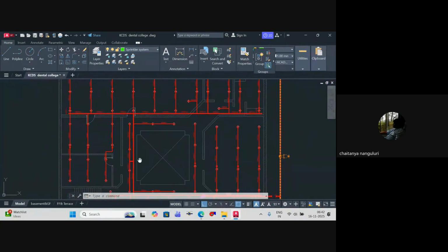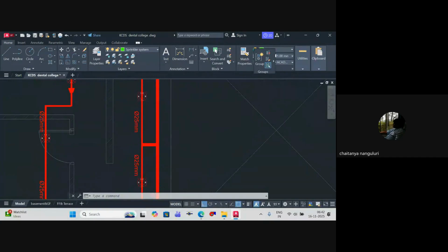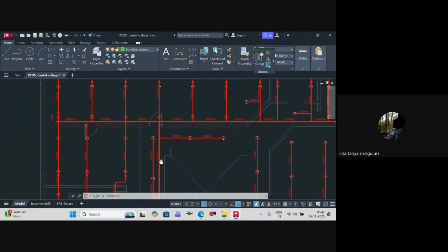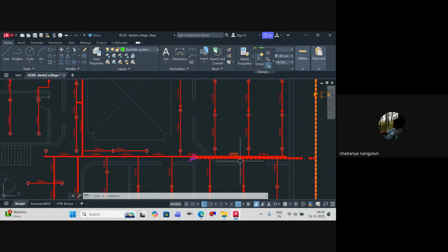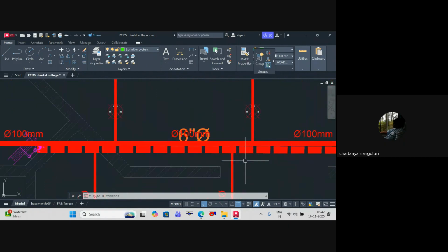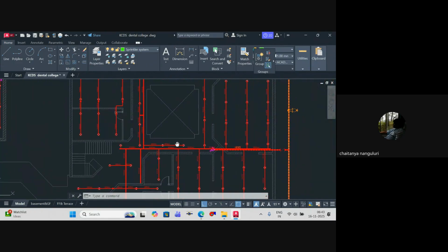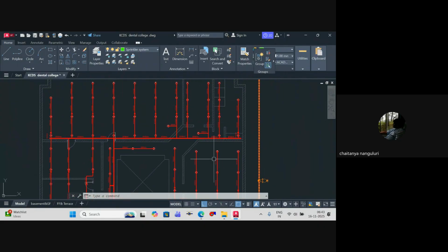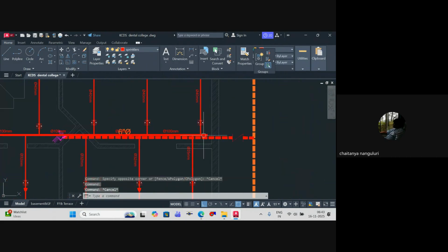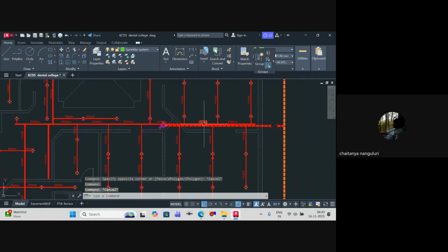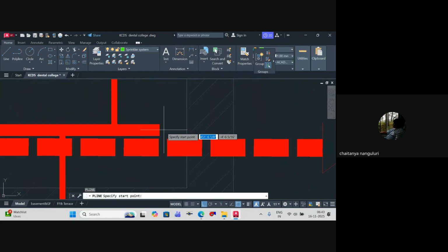Okay, so here we have taken it. There is some issue with the pipe size. Just a second. 150 dia, 150 dia, 100 dia is there. So technically, anyway, we have to adjust the pipe sizes. Probably I can consider this one over here as a dropper again. I'll increase the main branch, and now imagine the water is flowing from this direction to the other. From here, don't you think I can connect it or not?